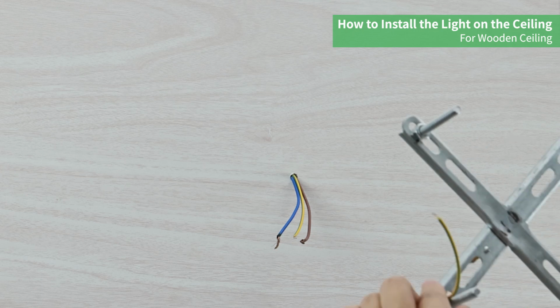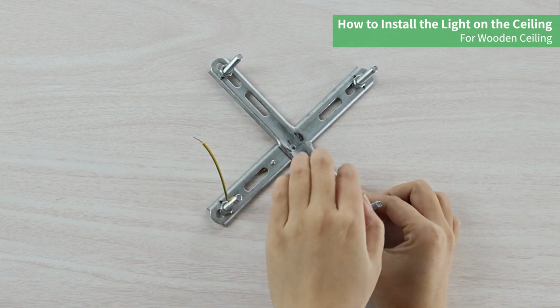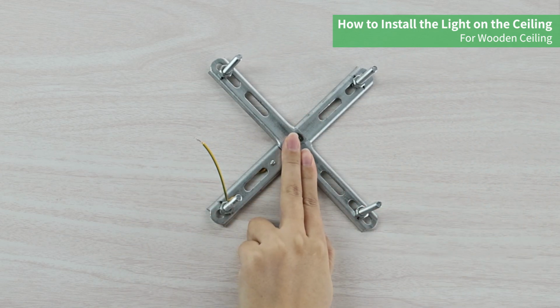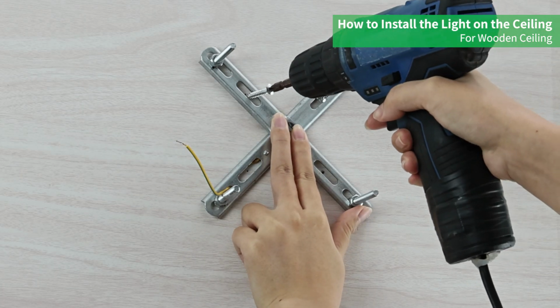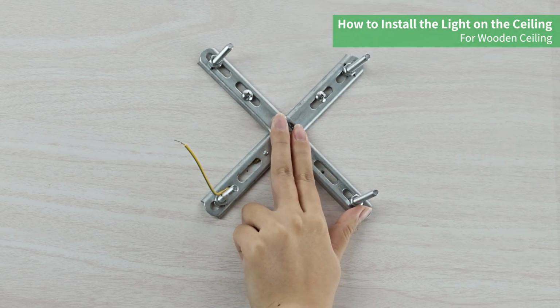For wooden ceilings, place the cross bracket steadily at the predetermined ceiling mounting location. Use an electric screwdriver to secure pointed screws into the holes on the cross bracket.